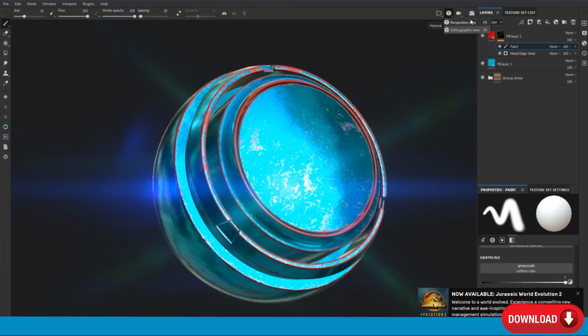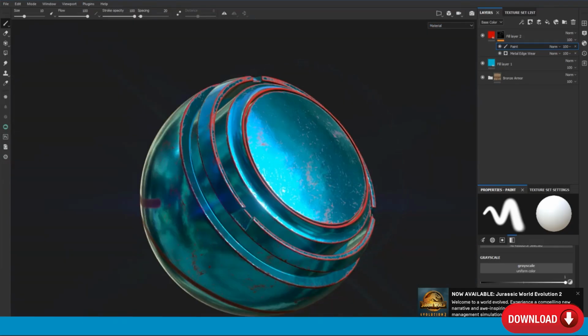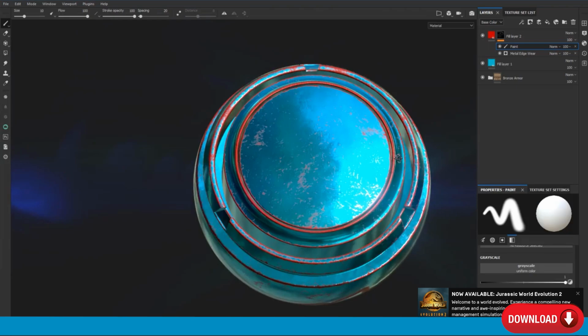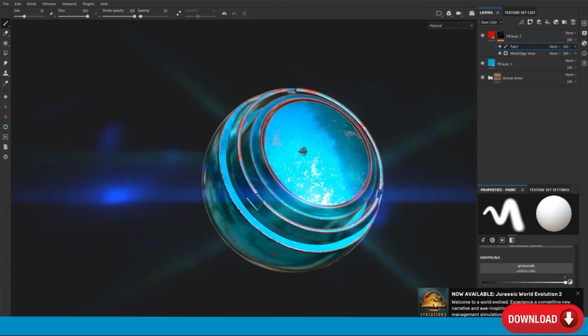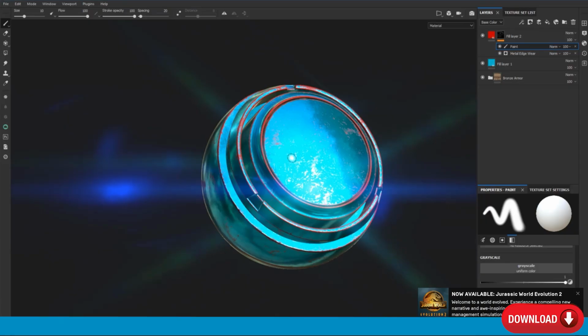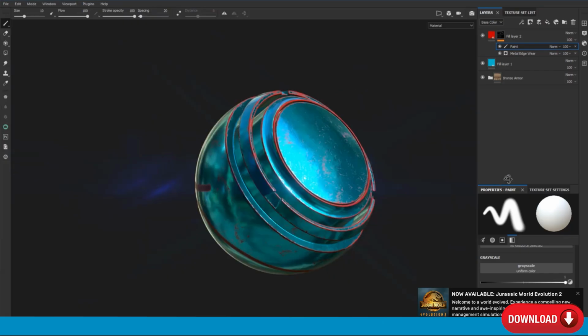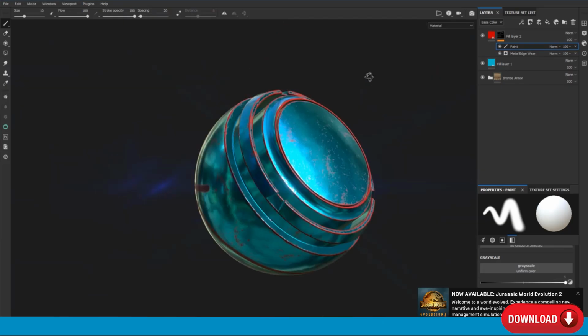So the next step we want to look into is perspective view and orthographic view. Orthographic is going to be flat, and because the object is not perfectly aligned, it's not going to work. But what it can do is, if you press Shift and Alt left, you can see it's snapped to 90 degrees perfectly. So this is our perspective view. I can rotate 90 degrees all the time, but my object is not perfectly aligned.